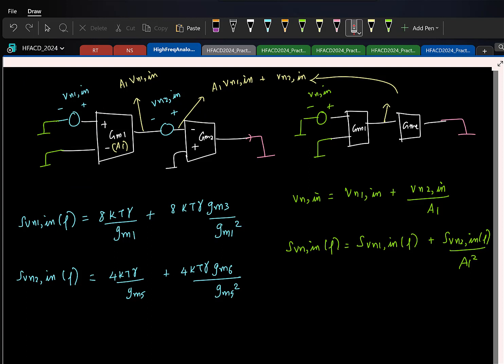That means that whatever signal I am adding, and you can think of it like this, along with this input voltage, this hypothetical noise voltage is getting added, and that is what is getting processed by your actual OTA. That's why we are doing this modeling.